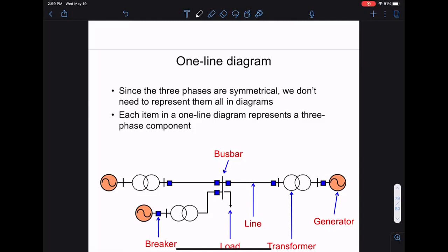So when we design it, we'll design the phases to be roughly balanced, right? We'll put roughly the same number of people on each phase. But in real time, what do we do? Switching. Right, we do switching. So a lot of times in a distribution system, switching is to balance the phase. You don't have to switch too much, because the areas are big enough that you have good aggregation, but sometimes you do a little bit of switching